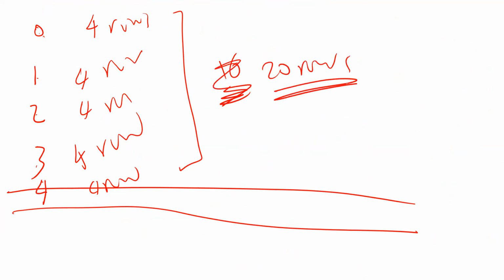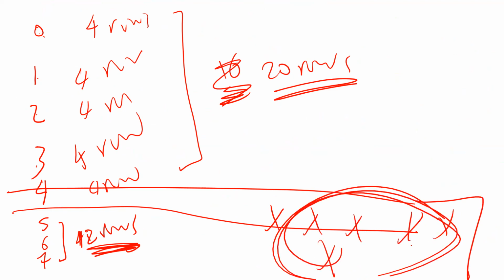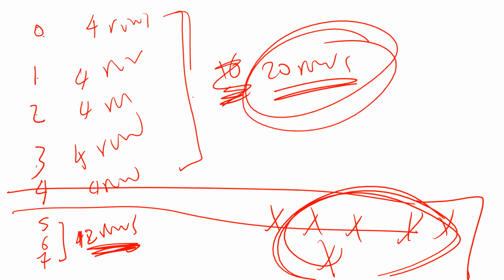After that you are going to have state 5, 6, 7. Everyone is going to be 4 times, 4 rows, so it should be 12 rows. For these 12 rows, the output is going to be don't care. You don't need to calculate them for the output, just put don't care. So all you have to do, based on the state diagram you have, is calculate 20 rows here.